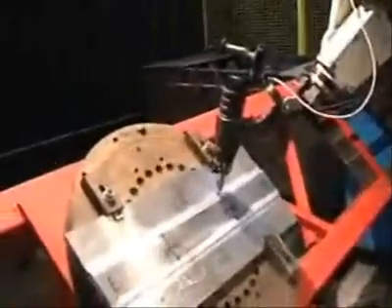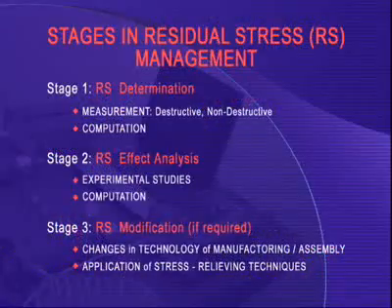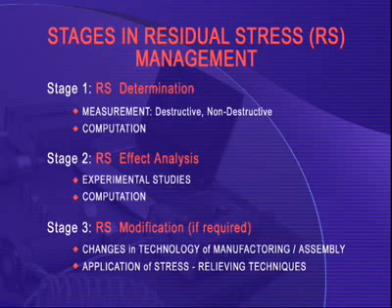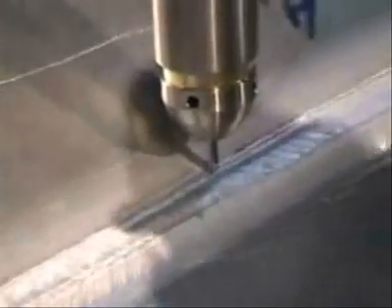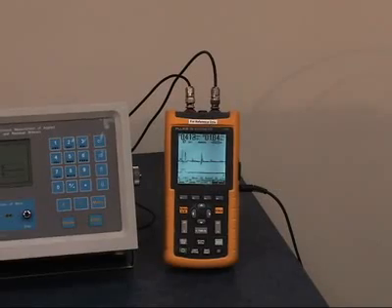The residual stress management concept includes the following main stages. Stage 1. Residual stress determination. Stage 2. Residual stress effect analysis. Stage 3. Residual stress modification, if required, that in turn includes the changes in technology of manufacturing, assembly, and application of stress-relieving techniques.